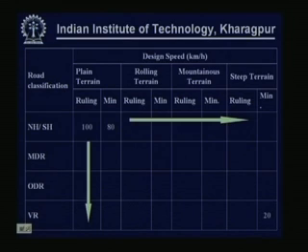Ruling design speed is the speed that we should target normally for the design of the roads. That means, ideally for a particular category of road and under a particular terrain, we must try to design the facility based on the ruling design speed.